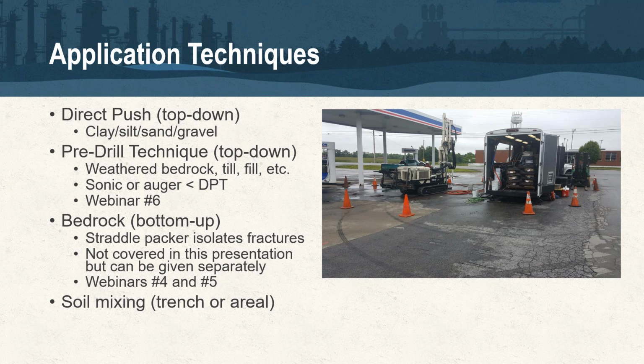So that pre-drill that I had talked about before, and that's the focal point of webinar 6, we're using that to get through, in situations where we've got weathered bedrock or glacial till. So in the Pacific Northwest or Canada or in the Northeast US, where we've got a lot of glacial till geologies, we can use this technique, again, weathered bedrock, or if it's fill material. We had a site in New York City, for example, where we're dealing with fill material.